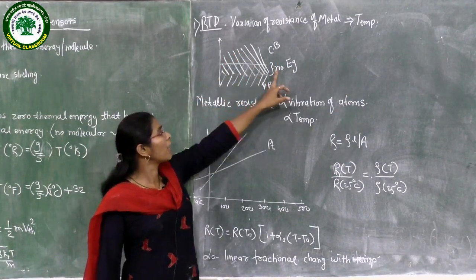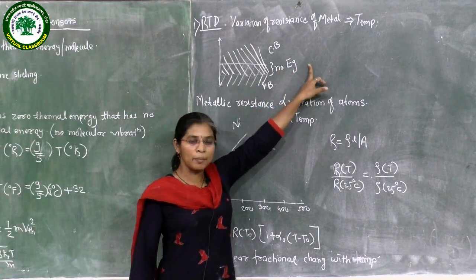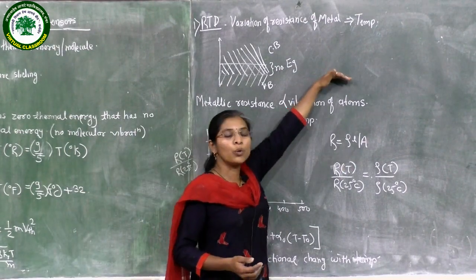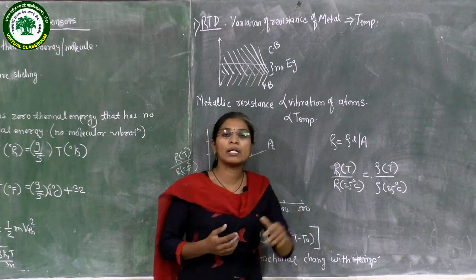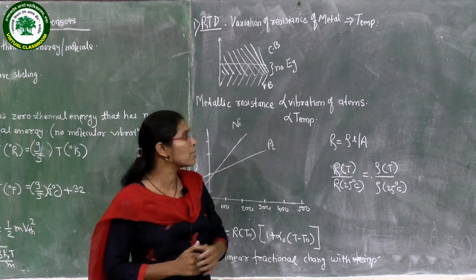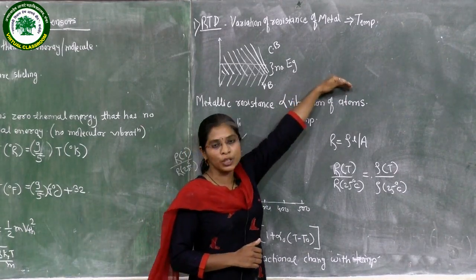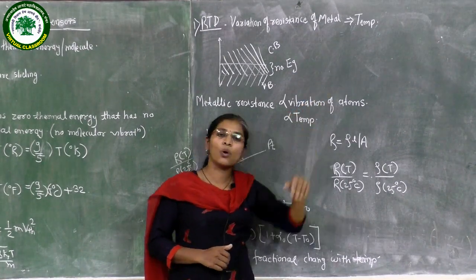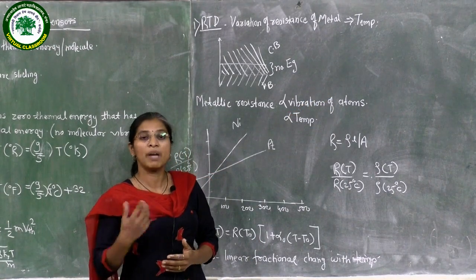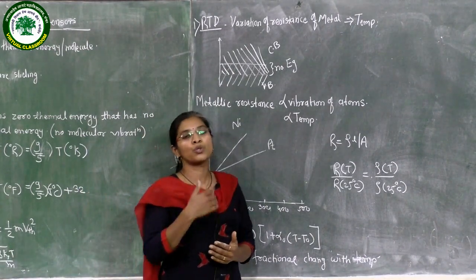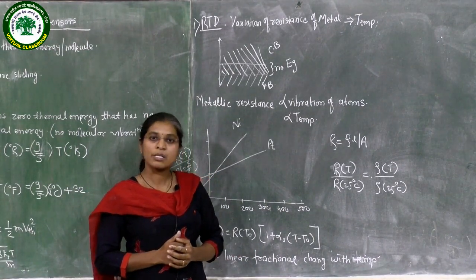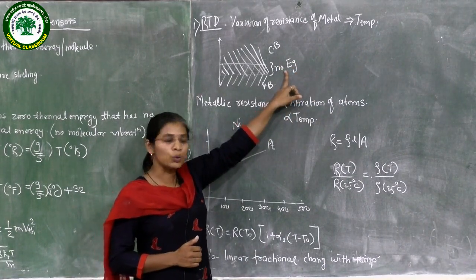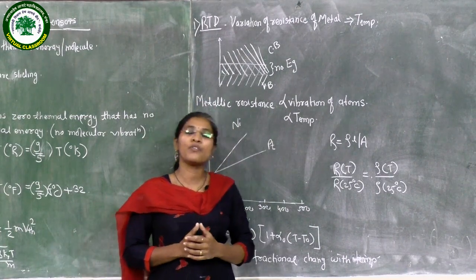As a result of that we have written, there is no band gap. So one can say from that, at room temperature many more electrons are present. Electron means free electrons or conduction electrons are present even at room temperature, or there is no resistance offered by metal to the flow or to the motion of free electrons or conduction electrons. So therefore we have shown there is no EG or band gap to the flow of motion of electrons.